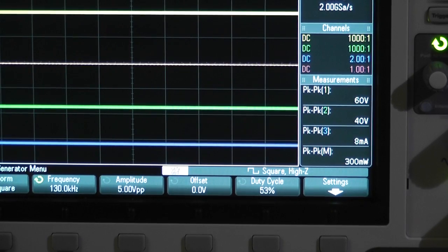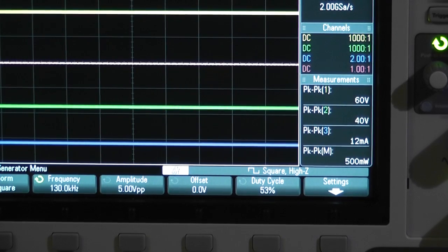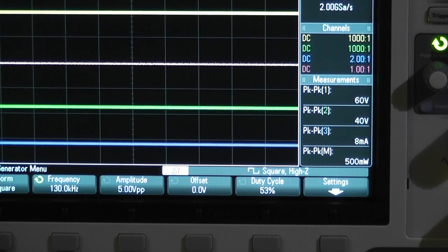You also have to apply a so-called differential measurement. What is a differential measurement? A differential measurement is when you take two measurements of a load or the device under test, DUT. You take the measurement on the load, on the wire, and you do a measurement outside of the load, close to the load, and you get a value, and this value needs to be subtracted from the value from the current.